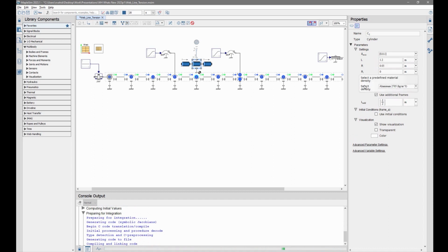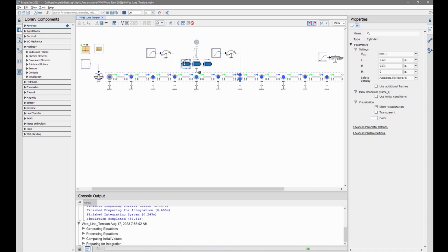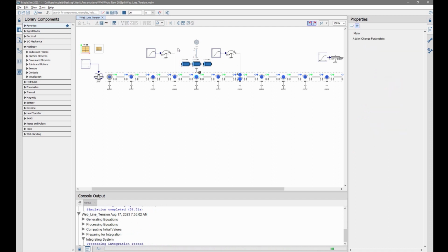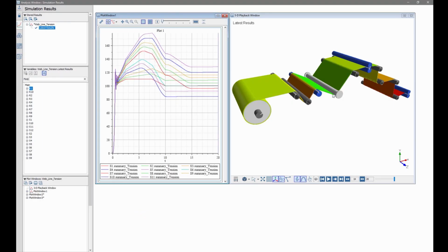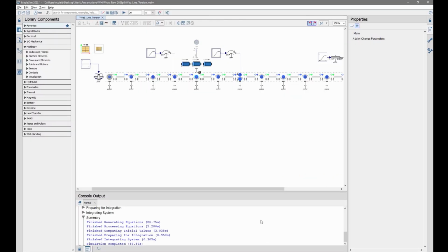Yeah, so the simulation is about to finish. All of these components I'm using from the machine elements, they themselves have geometry and density. So MapleSim then sums them together and correctly accounts for the total mass and total inertia of all the connected parts. And that will affect the overall tension. So we see that here's the shape I'm using for this simple demonstration. Still a complete and correct simulation, except that the mass and inertia of this roller, it is a rotating roller, is now defined externally.